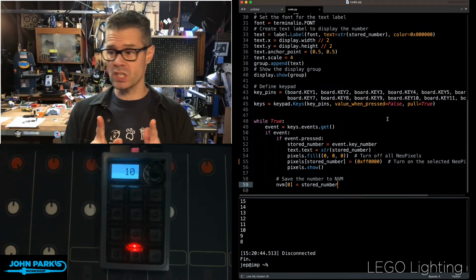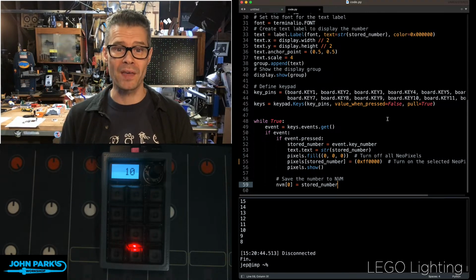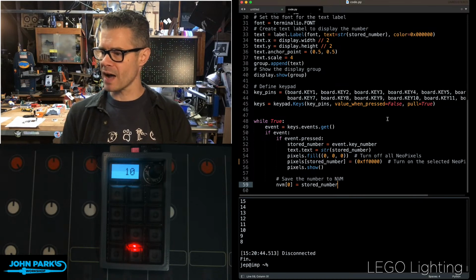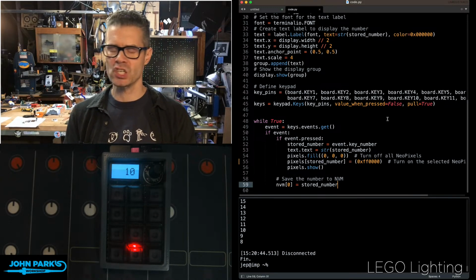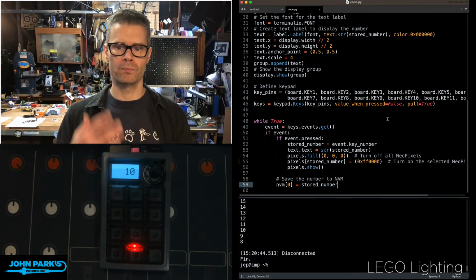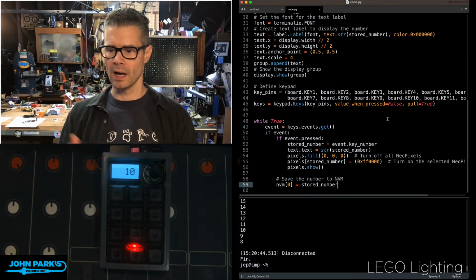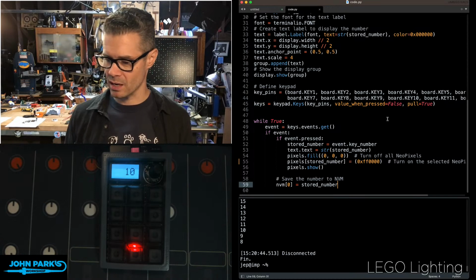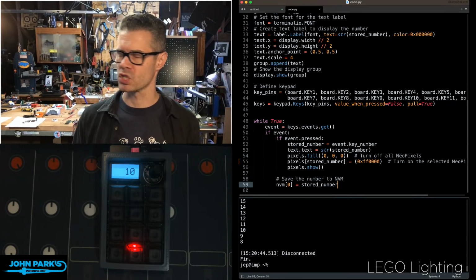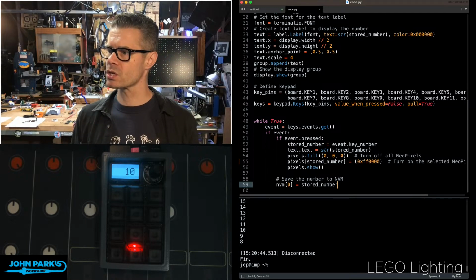A couple of statements and questions in the chat. DJ Devon3 says, the non-volatile memory also persists even if you reinstall CircuitPython. I had no idea. That's really cool. P. Curry in a Hurry has a question. How many writes does the NVM survive? Are we talking 100,000 writes like Flash? Yes, this is Flash. It is part of the Flash memory, so it's not some low number like 10,000 or something like you'd find in other parts of memory. So you can write to it a lot. If anyone knows the real numbers on that, please speak up in the chat because I'm not sure. But it acts like it is actually part of the Flash memory on the chip. It's just that CircuitPython carves that out and treats it a little special.